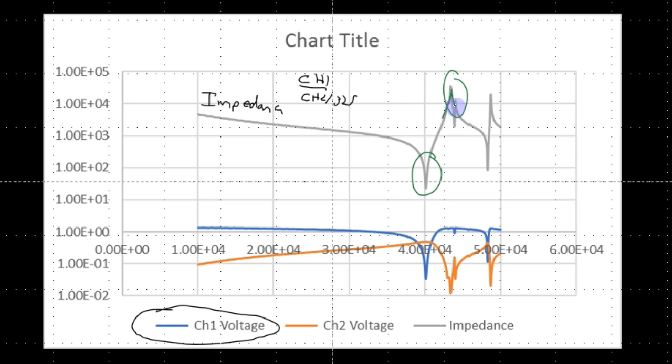And we also have another dip here. When the impedance is lowest, we have the resonance frequency, and when it's highest, it's the anti-resonance. Now I can't exactly say why we have a little bit of noise here. It could also have to do with other nonlinearities which exist in the system. But typically we would not have as many features there. This is the second resonance, which is something we would normally try to design out of our system. However, when we attach this to an external structure, this resonance is going to behave significantly differently, and we probably won't have this type of behavior around.